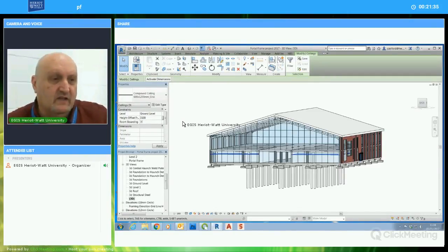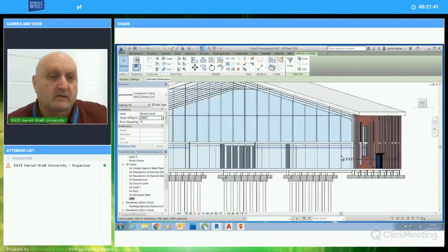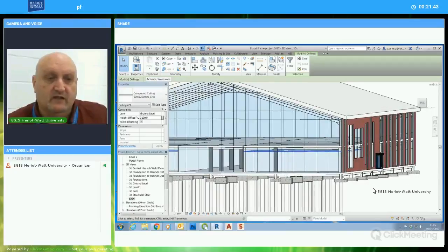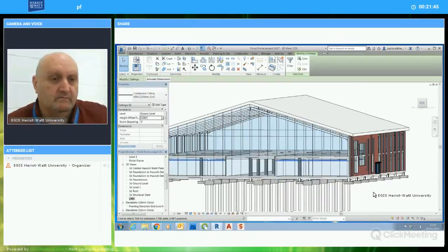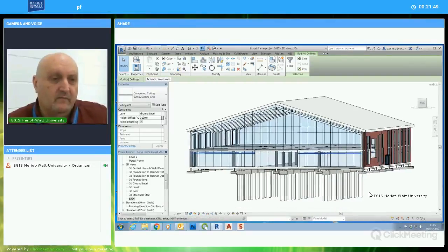Anything over 3 meters is fine, and that just makes the void here for air conditioning and piping and things big enough, but it's not ridiculous. 3.1 is a good height for a commercial ceiling.